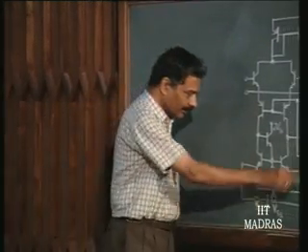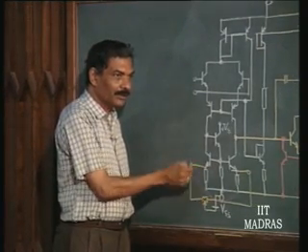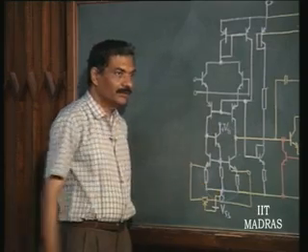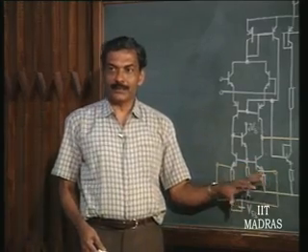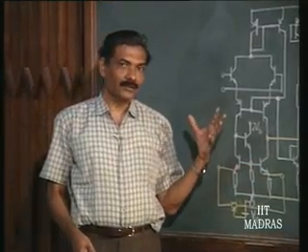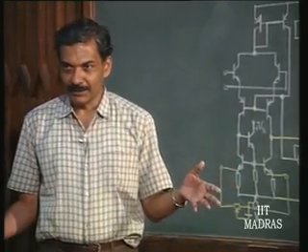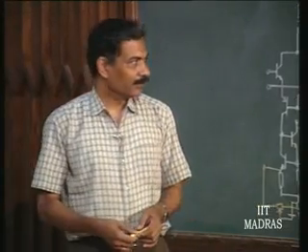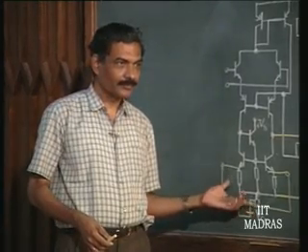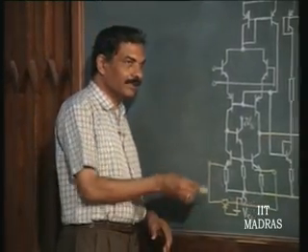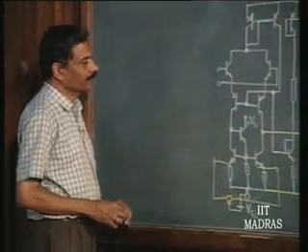So, this is an externally connected component, okay, which is nothing but a potentiometer with the center tap connected to minus Vs, that is all. So, this kind of compensation is available in certain 741s, where these terminals are brought out. If these terminals are not brought out, you cannot compensate for it, obviously. Right. So, in certain packages you will find these terminals are in fact brought out. Okay. So, then compensation can be easily done using this procedure. Is this understood? This is one thing special about it.